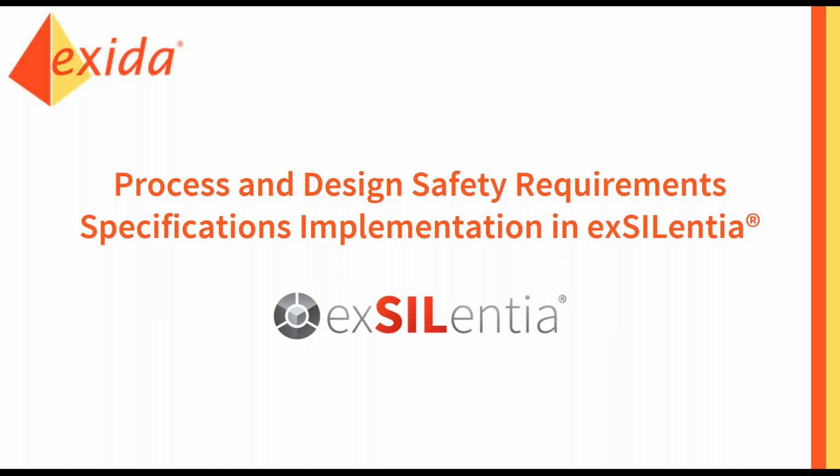Someone asked, what is the output from exSILentia for the SRS? Is it a report per SIF or a complete report for the whole safety instrumented system? Again, my sample project was just one SIF, so this might have been unclear, but it does both. It tells you all of the requirements for your complete safety instrumented system, and it dives into any SIF-specific information. So all of your SIFs will be listed, and all of the specific information for each will be listed. So it's everything in one report. It should be one handoff that you have to make to the design team, and then eventually from the design team to the implementation team.